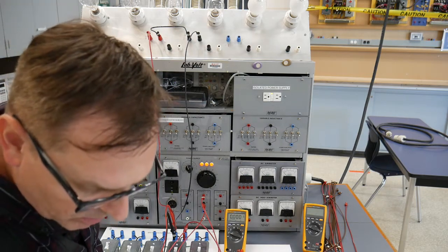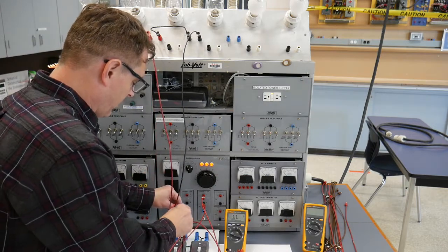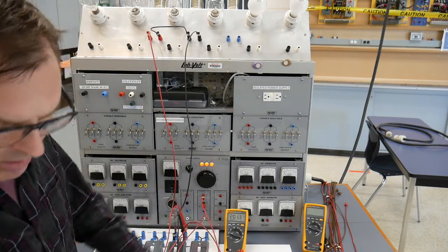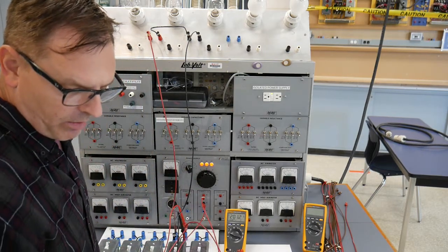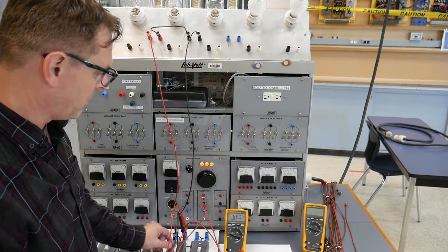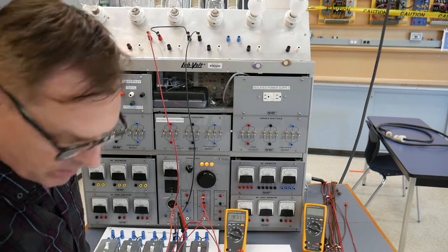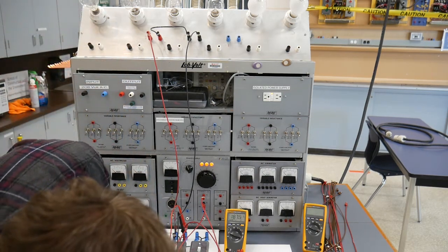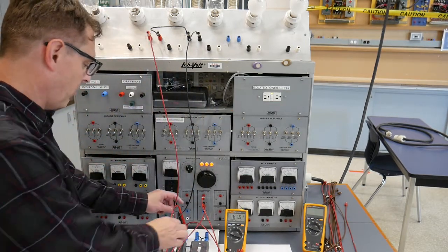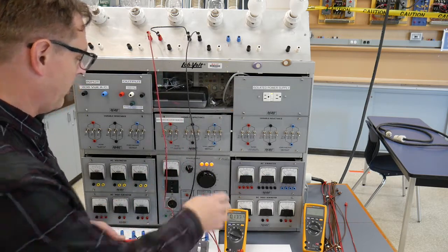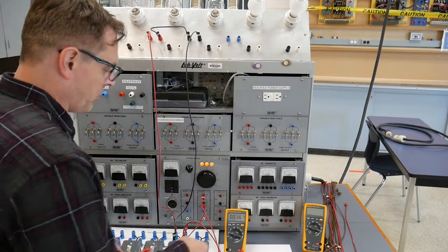Okay, switch terminals A2 to B2 with the switch closed. Now we're moving to the other side of the switch, the primary side, closest to the source. We've got 200 volts there. We're fluctuating again. And then we're going to stay on the same side. We're just going to turn that switch open. With it closed or open, we should still see we've got 186. So we should always see line-to-line voltage on the primary side of that switch, or on the beginning side, regardless of the position of the switch open or closed.